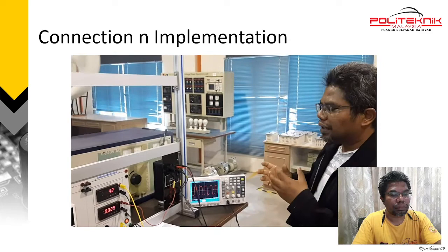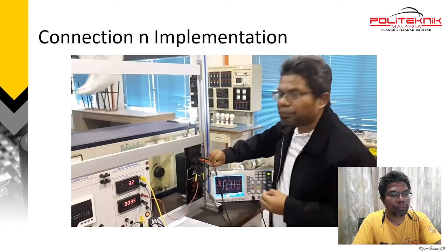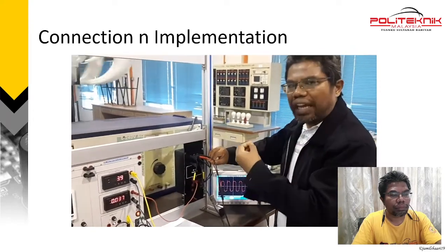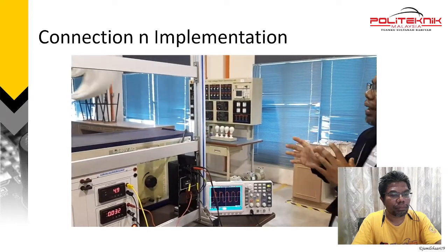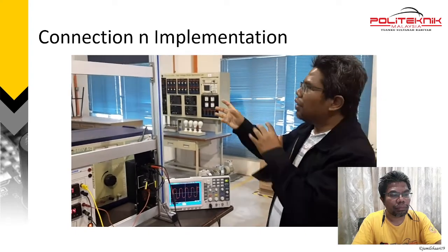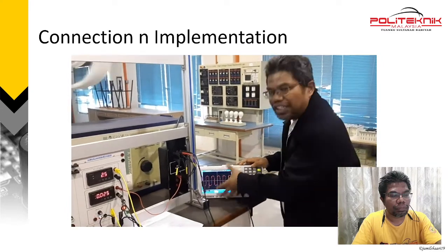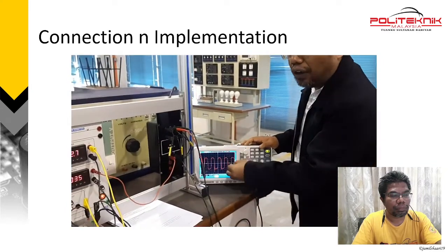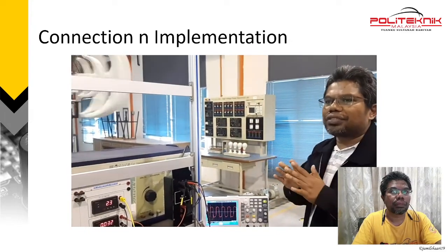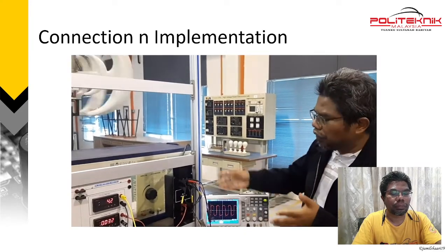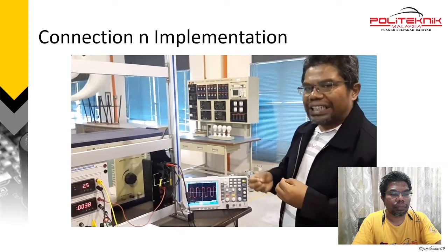In real stations, it is not direct DC, and also why we should convert it. We teach them why we should convert it into DC first, not just put the AC output directly. Because of the frequency, we can show that the frequency of the AC generated by the wind turbine is totally different. It's not synchronized with the grid. So we have to convert it to DC first. This is one of the methods before the integration to the grid.